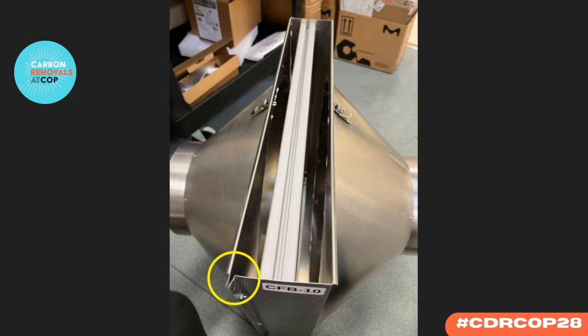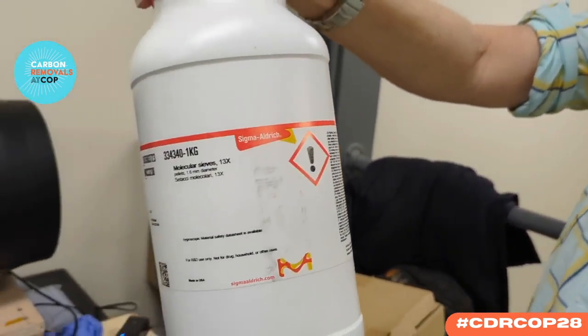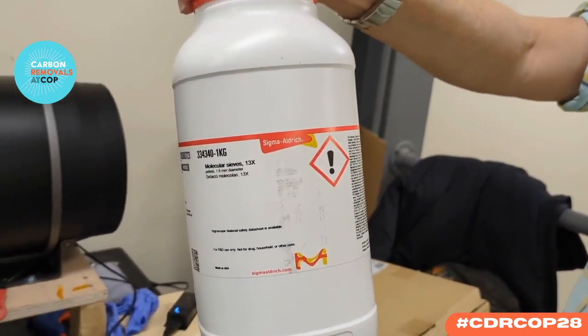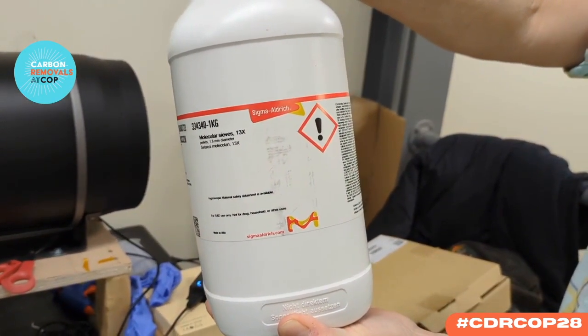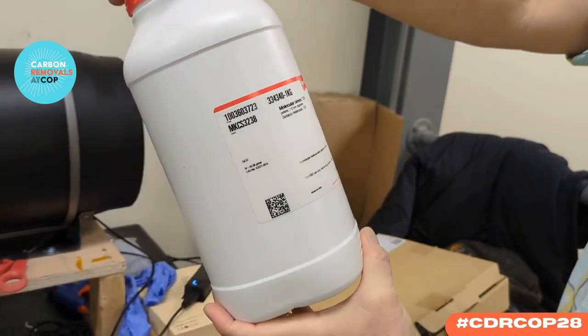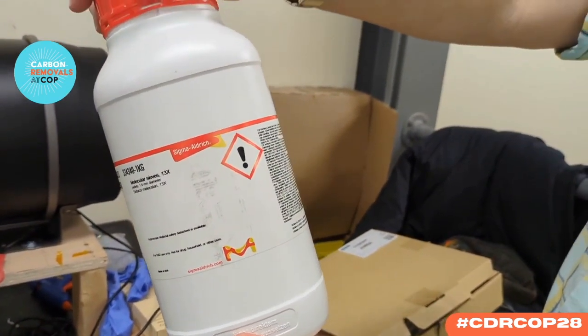Yeah. Well, vacuum we'll move on to next, but let's say this a little bit. The sorbent is the heart of the thing. And I have an image here that Seth actually shot recently. I can show a little bit of a video here, and you can see what type of sorbent we used. Again, David? It's a zeolite. It's called 13X. It's also called a molecular sieve. And it's the only one that was affordable that we could actually buy commercially.